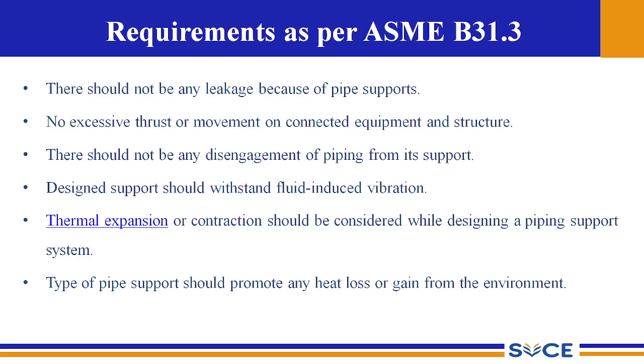Another example I can give you is improper installation of hanger supports, because hanger supports are normally placed at a higher altitude. When hanger supports are not installed properly, additional swaying of the pipeline can happen. Because of that, inducing moments on the structure will happen, and the disengagement of the piping along the support can happen.